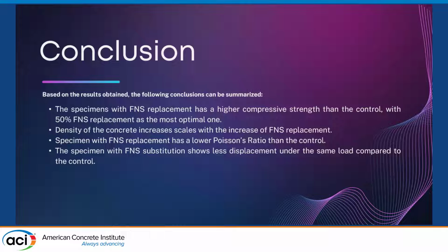The second conclusion is that the density of the concrete increases as the ferronickel slag replacement increases. So it has to be our concern if we are going to make a model of a structural element, because it may affect the structural system as a whole.